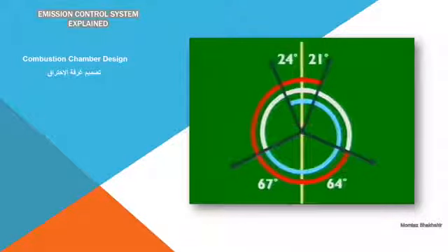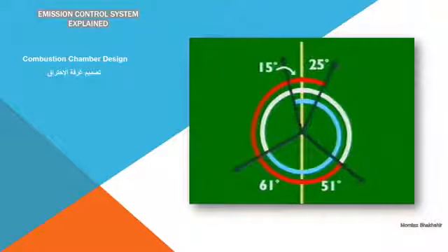Changing valve timing also alters the combustion process. Reducing valve overlap reduces the scavenging effect. It also reduces hydrocarbon emission.